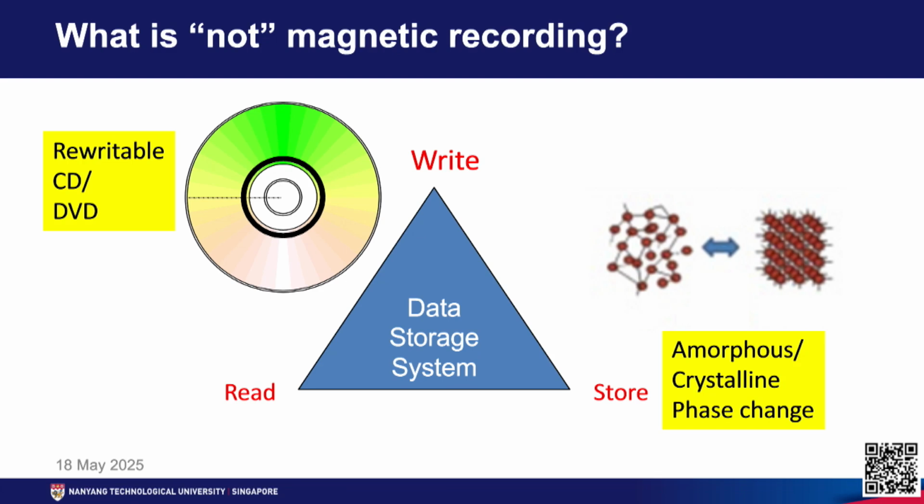If you heat this material slowly and cool slowly, you will have a crystalline structure. If you heat it and cool rapidly, it will become amorphous. By the way in which you heat and cool, you can transition between amorphous and crystalline phases. The reflectivity of the material will be different in the crystalline and amorphous phases.